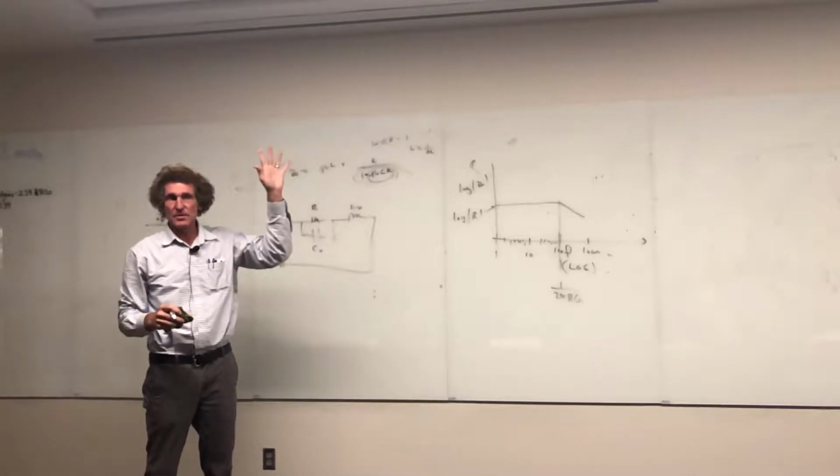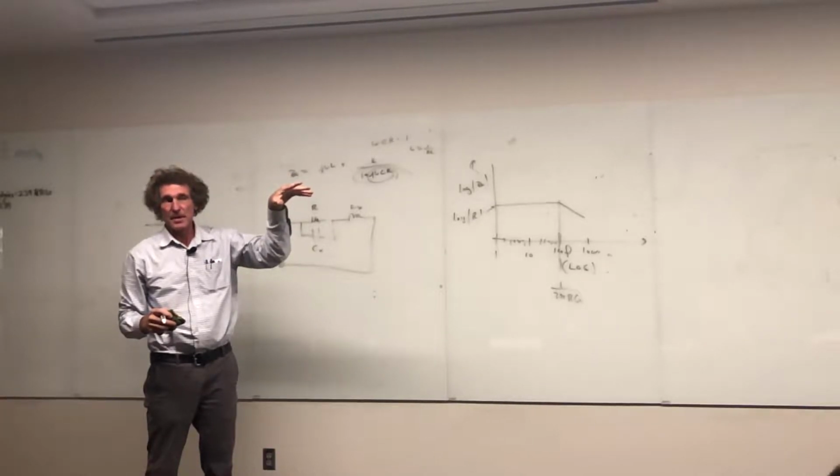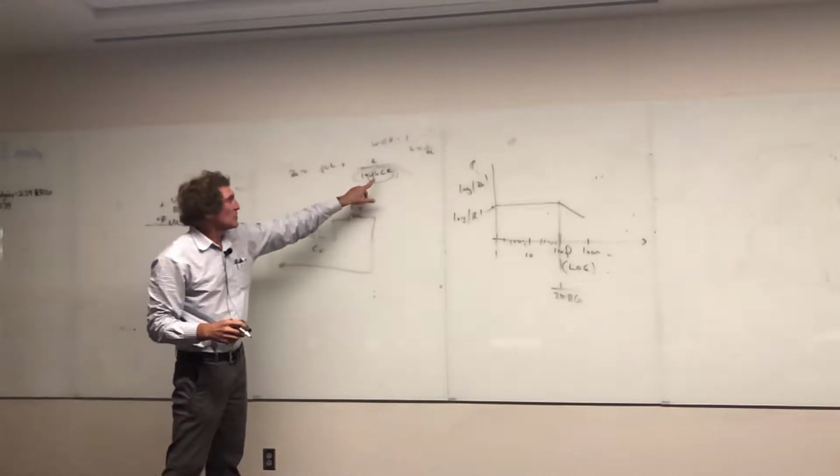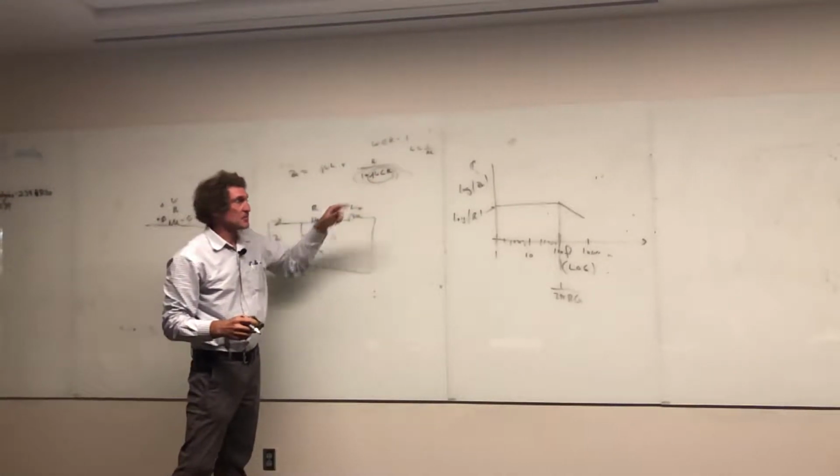Give me a show of hands if you do. All right, omega is always 2 pi f. And what we're looking for is when this all of a sudden becomes 1, omega times C times R. Did everybody follow me? That's the first break frequency.